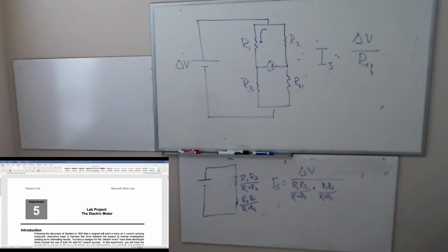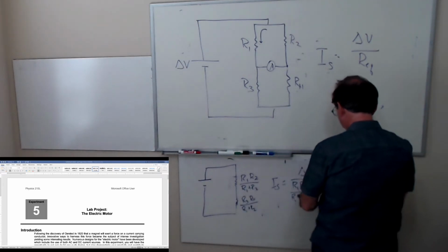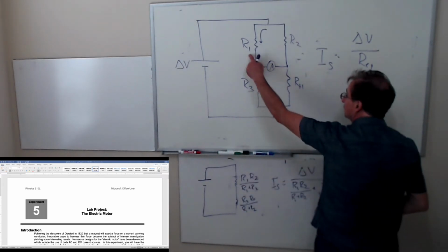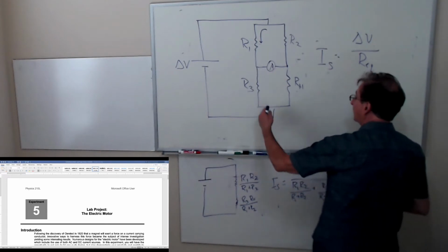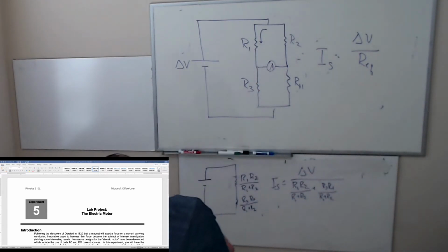I do it in terms of all the resistor values and the power supply voltage. Okay. The rest of it's easy now because I just said take this times this, that'll give you the voltage across that. And then I divide that expression by R1, done. Of course, you might have to simplify a little bit, but I don't know how much simplification there is.